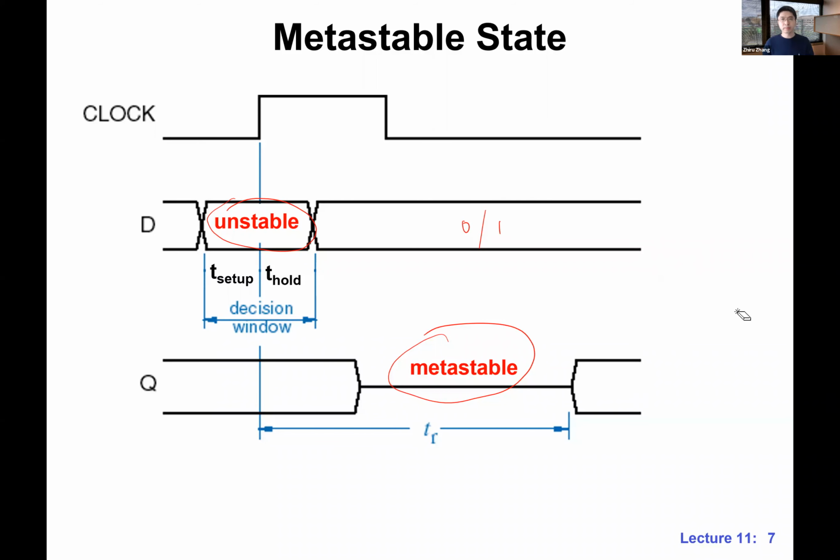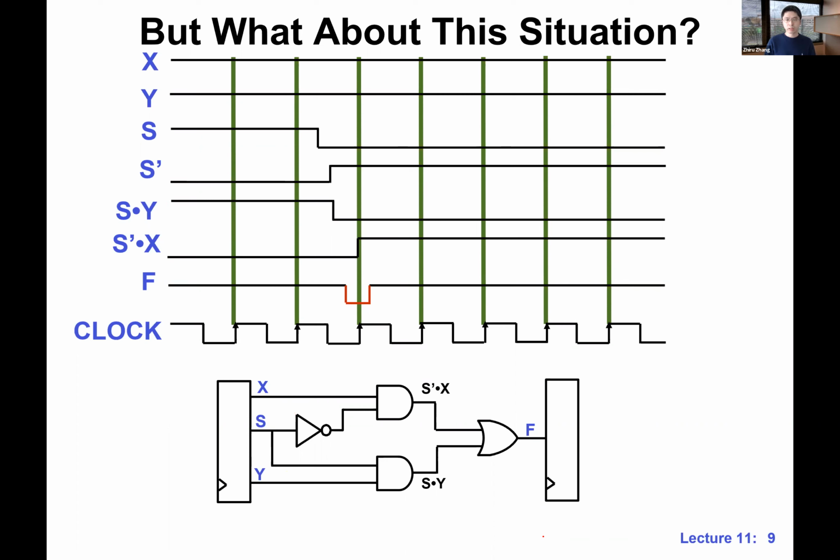So see here, in this case we have a wider cycle time, a wider clock width. In this case, this is where it's good. And in the second case, this is a bad situation. We sort of narrowed the clock width, so we are running at a higher clock frequency. If you're not careful, indeed, some glitches may cause us issues. Hopefully this is intuitive enough.